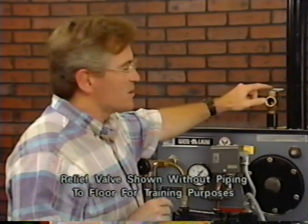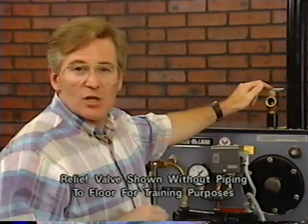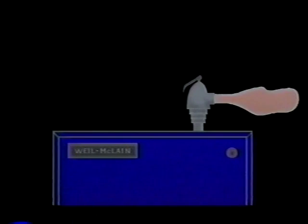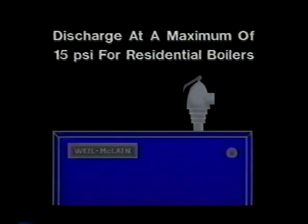On or near the top of the boiler, you'll find the steam pressure relief valve used to protect the boiler from excessive pressure. This is similar to the pressure relief valve on a water boiler. However, the steam relief valve relieves excessive pressure all at once. For cast iron steam boilers, these valves are set to discharge at a maximum of 15 psi.